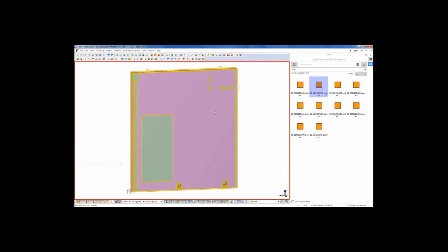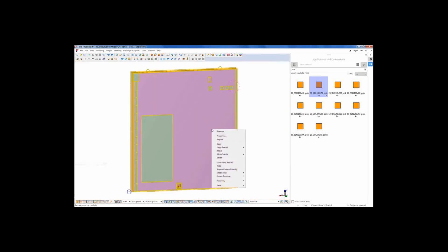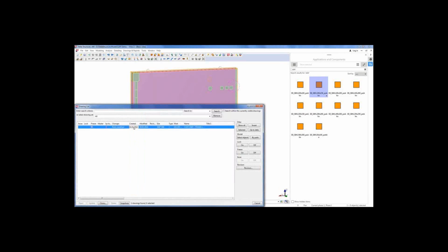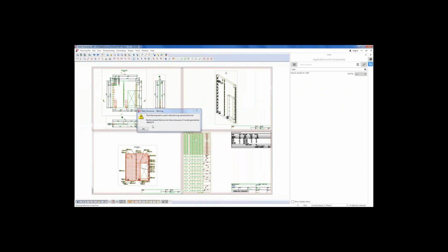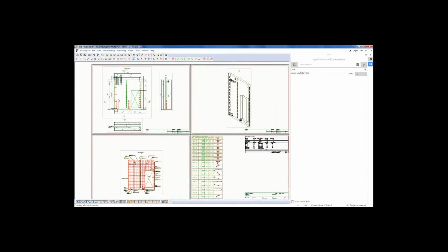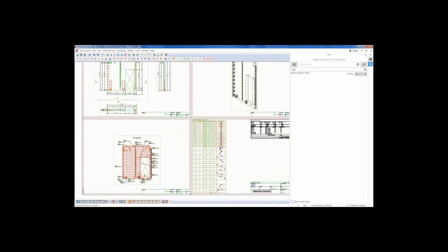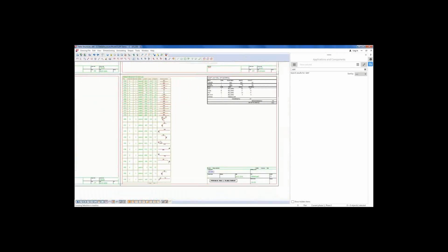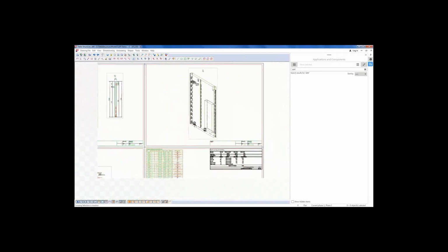And now there is always, we send also the drawings. So let's select the element and create cast unit drawing. And now here it is. Let's open it. So here we have the drawing that we just created. Here's the formwork with all the measures. Here is the reinforcement with marks, bar bending schedule with all the rebars, material list of the quantities, 3D views.